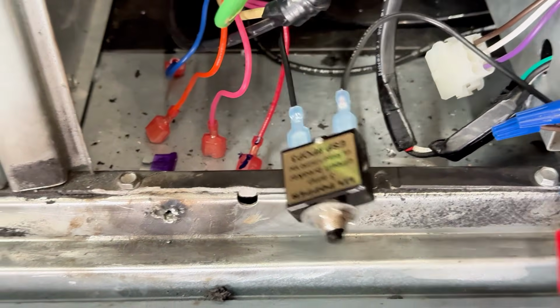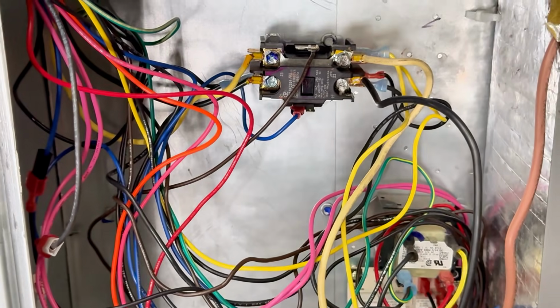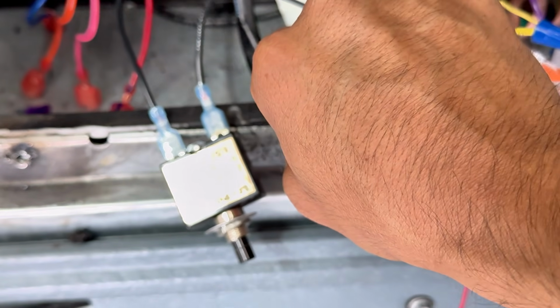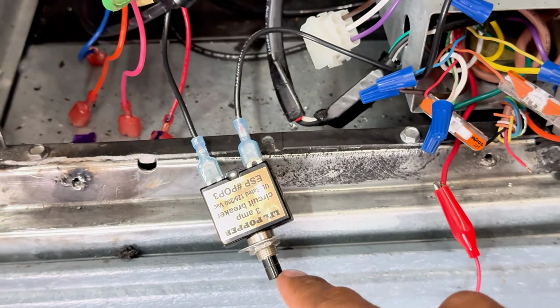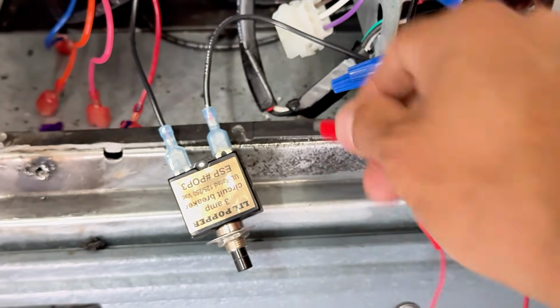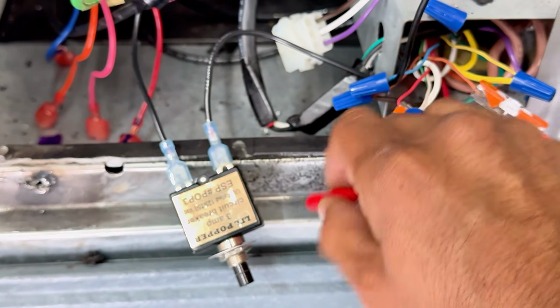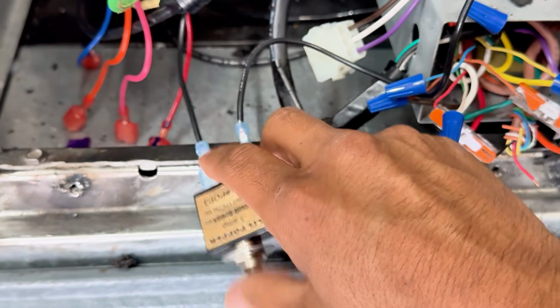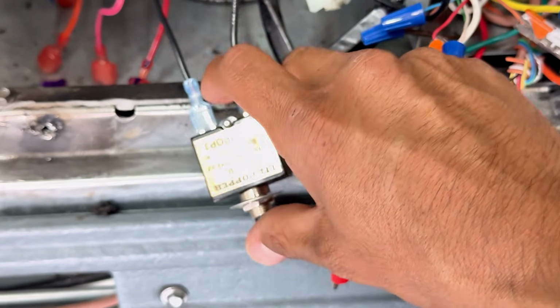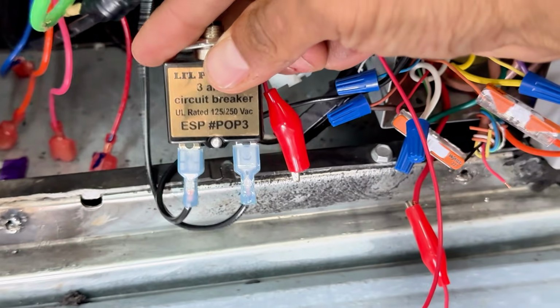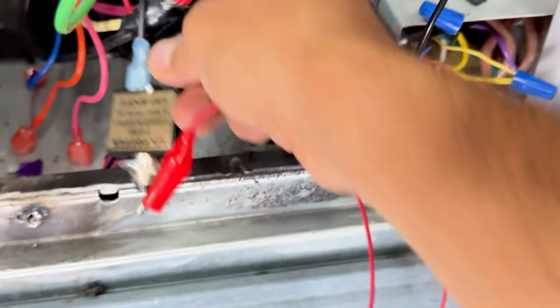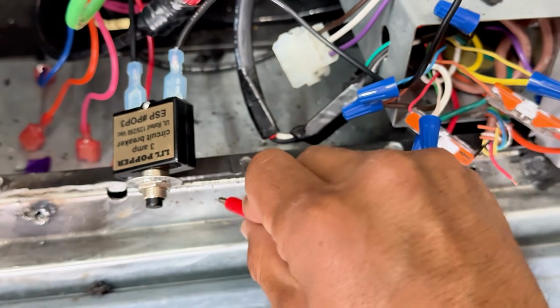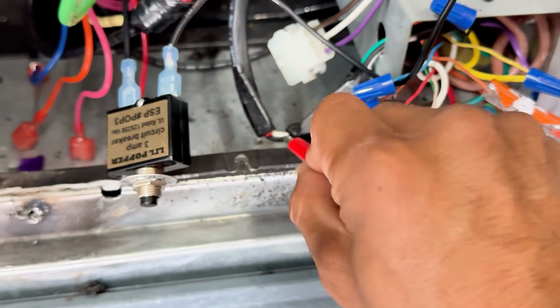And then this right here. Because we said all this is common, the whole metal, because common is grounded to the metal. Let's go ahead and see that. There we go. You saw that? It popped the fuse. You probably saw the sparks right here, right? All I did was just kind of hold it in place because it needs to pull enough amps. I believe this one here is 3 amp. I'll do it again one more time. But you see the spark? You see that spark right there?